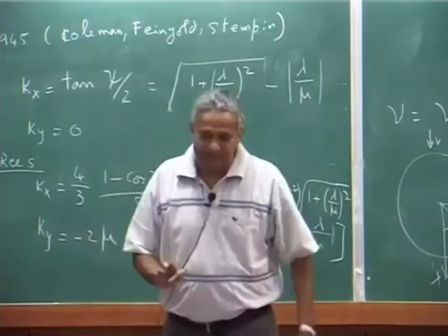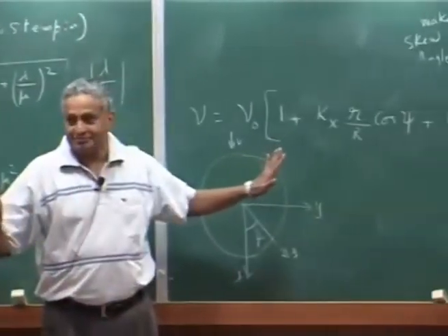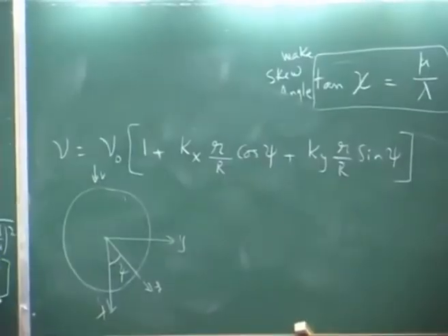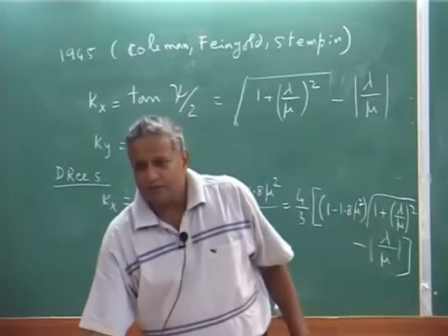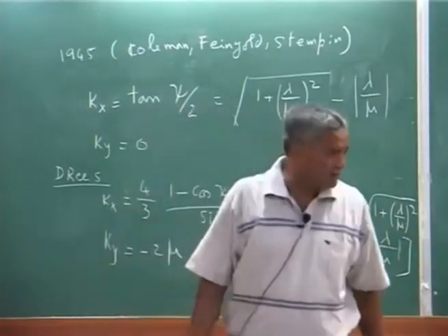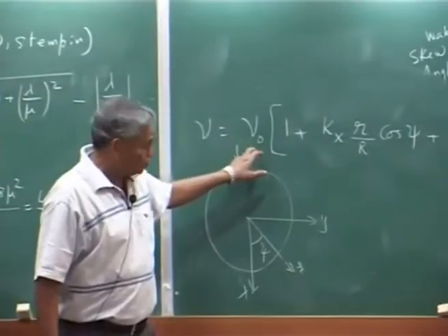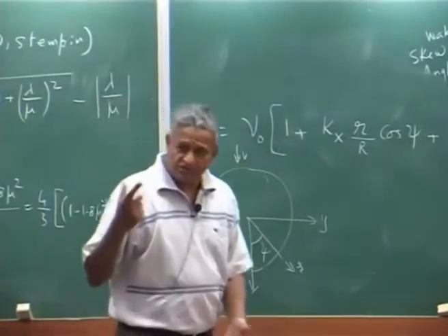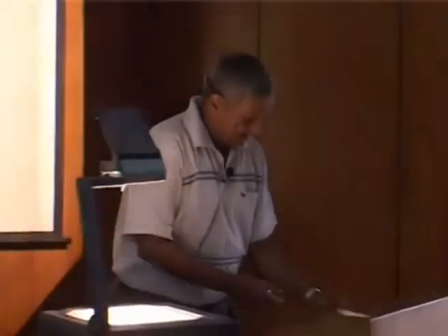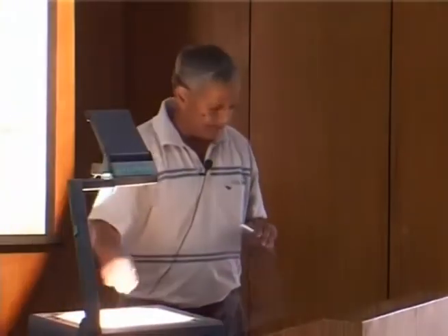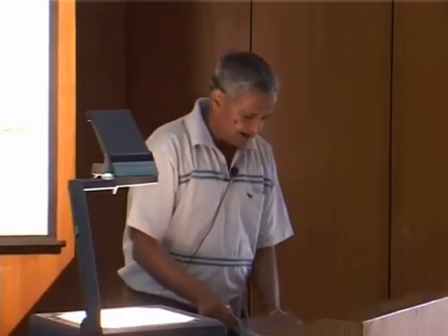Now we got an expression for inflow in forward flight. Good. Let us now go back and actually start. We learned momentum theory. How do we apply it? Because you know that for you to get this nu naught, you need to know CT. And the CT was given here. Please remember, CT is given here. Lambda I to CT expression is right there. Now I will close this here.